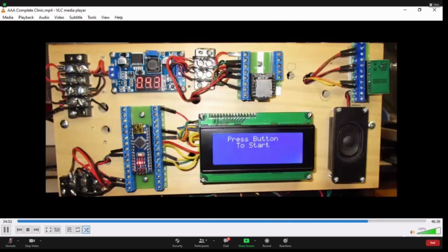Like the Waterfall, this project is going to use audio, so like before, I wired in a buck converter, barrier strip, MP3 player, amplifier, and speaker. The motors for the lumberjack and the tree both require between 4.2 and 5 volts, as well as ground. And fortunately, we have that coming out of the buck converter.